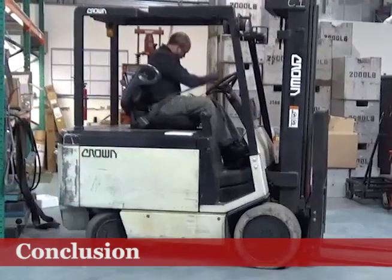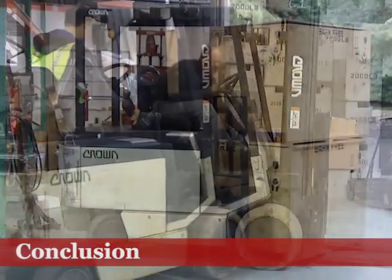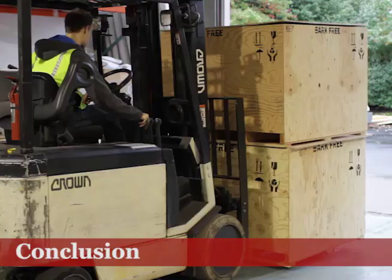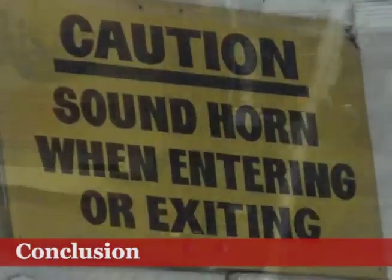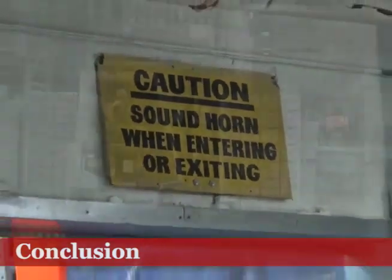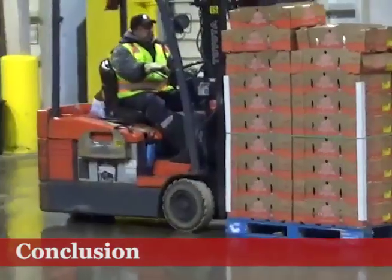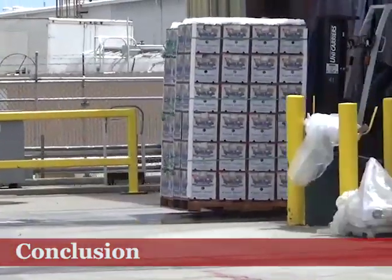Wear a seatbelt, and know the appropriate actions in the event of a tip-over. Make sure the loads you lift are stable, and within the capacity of the vehicle. Always look in the direction that you are traveling, and use the horn to communicate with drivers and pedestrians. Travel with the load low to the ground. Remember that low, and slow, will help keep your forklift's center of gravity in the stability triangle. Thank you for your time, and drive safely.